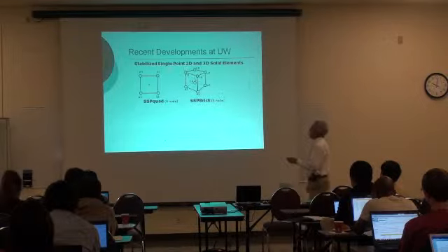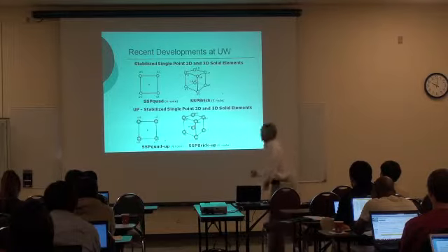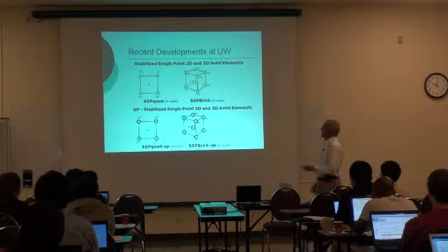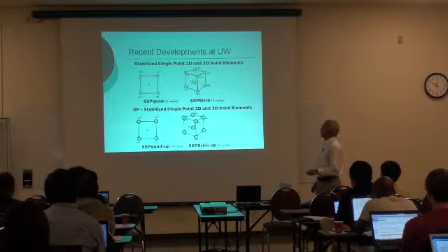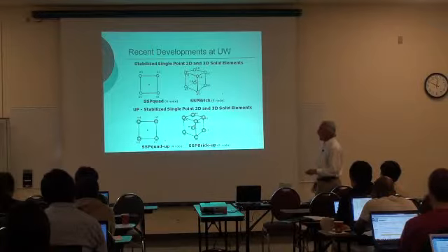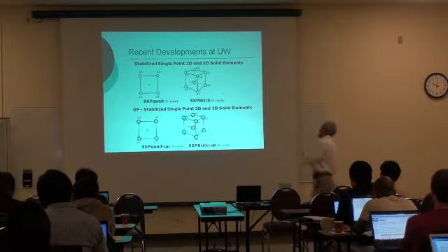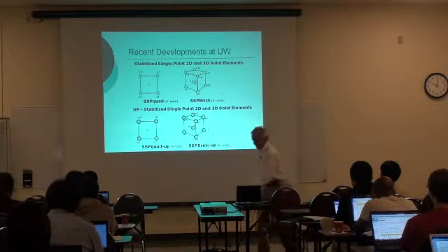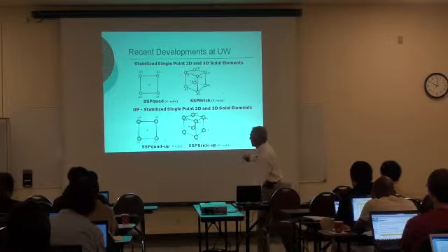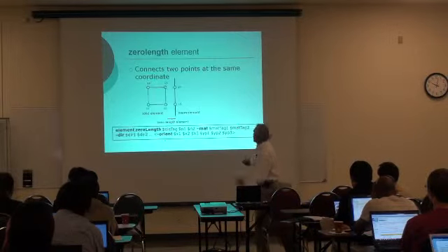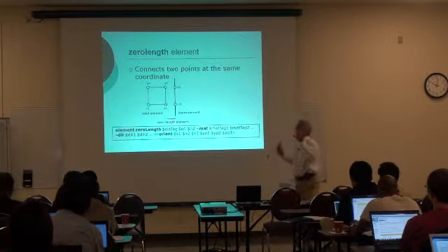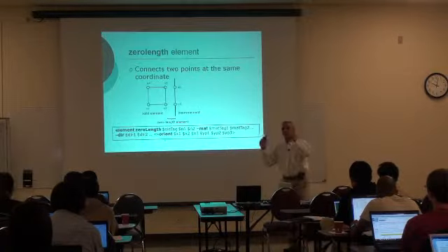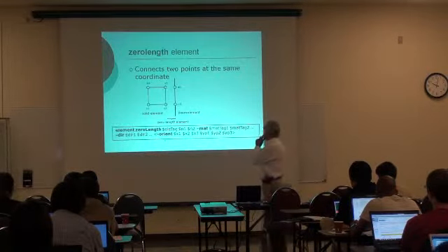So this is for a single phase. We have also extended that to the multi-phase elements. That means we have a stabilized single point quad UP that allows us to represent the solid and the fluid, and also a stabilized single point brick UP that allows us to characterize the behavior of the saturated soil in 3 dimensions. That's all I will say about the solid elements that are available right now in OpenSees.